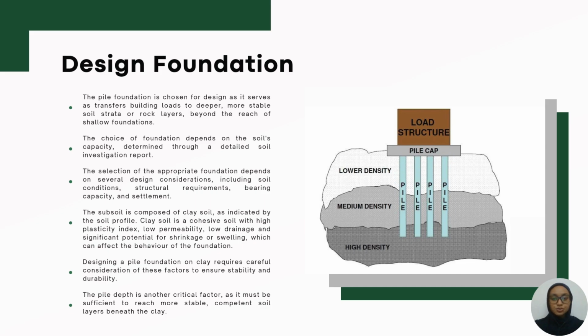The pile foundation is chosen for design as it serves to transfer building loads to deeper, more stable strata or rock layers beyond the reach of shallow foundations. These foundations are commonly used when surface soil lacks sufficient bearing capacity or when structural loads are exceptionally high or the soil near the surface is weak or compressible. However, the choice of foundation depends on the soil's capacity determined through a detailed soil investigation report.